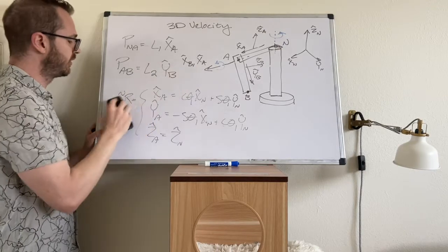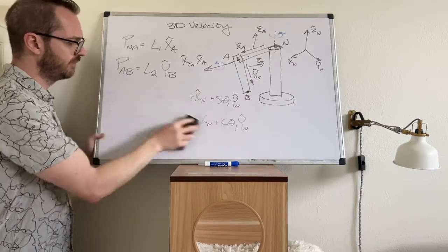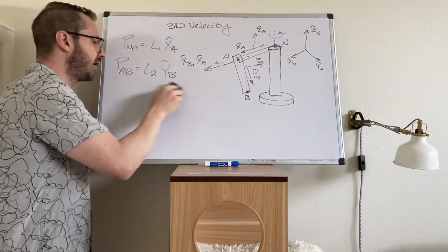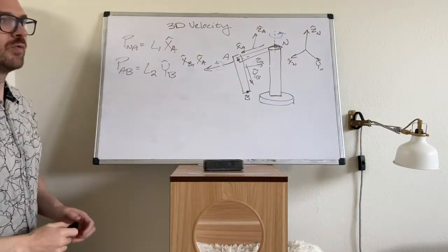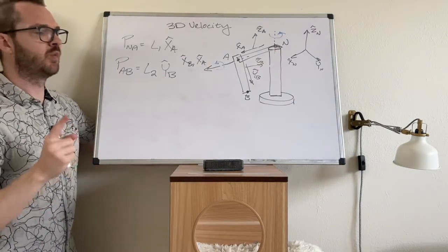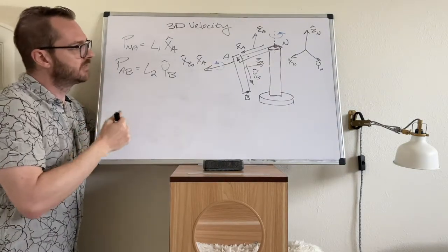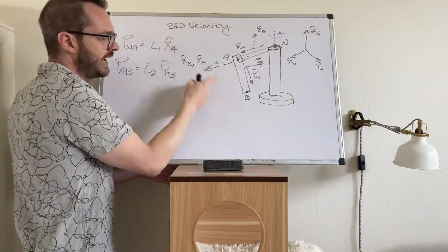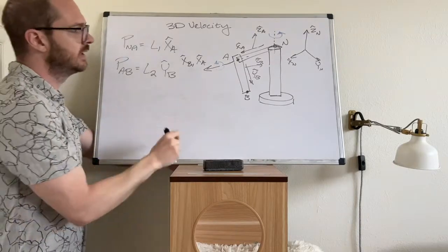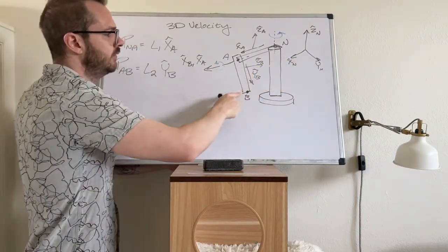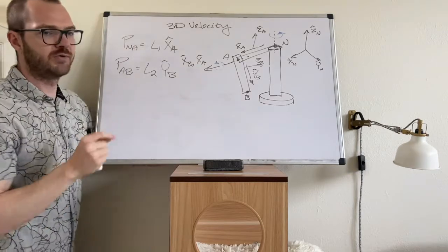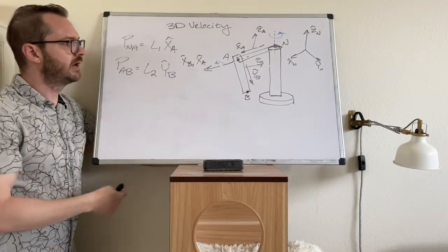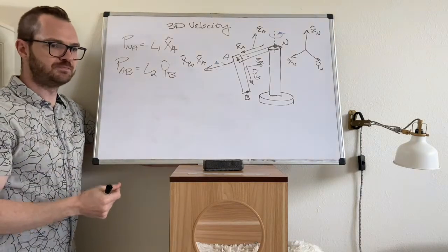Next, let's define the rotation of the B frame. We've talked a lot about using relative or absolute angles. In this problem, you have to use relative. Why have to? Because consider there's this first axis that's spinning, and then we're spinning around this shared x. You cannot get from the N frame to the B frame with one simple rotation. You can't do it. So in order to define it, we need to use relative angles.